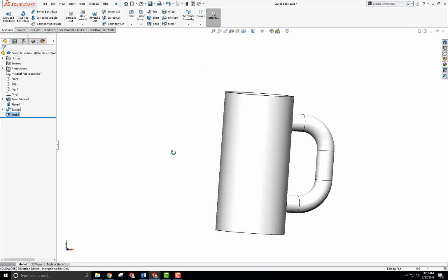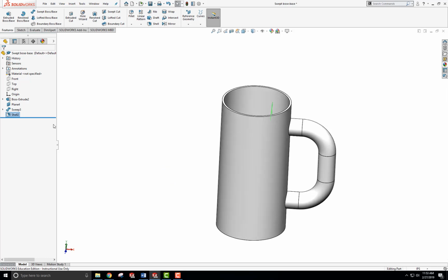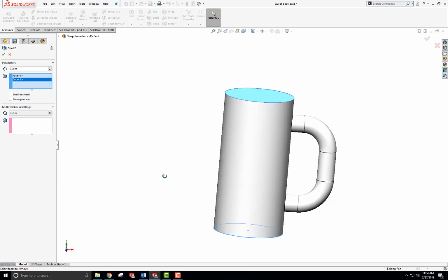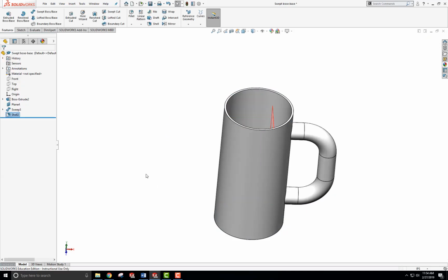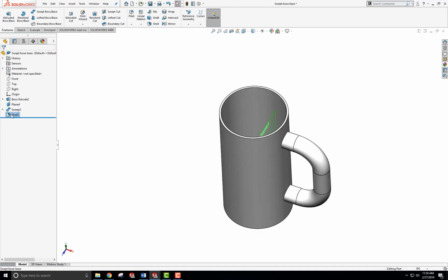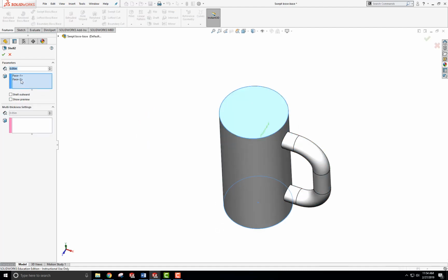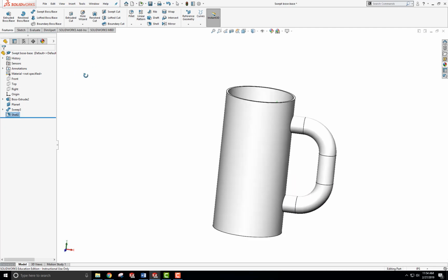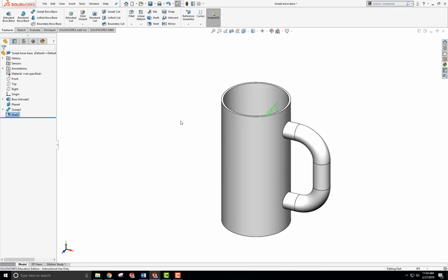Okay. So just so you know that. And if I edit that, by the way, and choose both surfaces, it will open those both surfaces up like this. So they're both open now. You can see through them. Okay, but I'll just leave with one for now. So I'll delete the second one. Right click and delete that, and we're good. Okay. So that's how you do the shell command and a quick wrap.